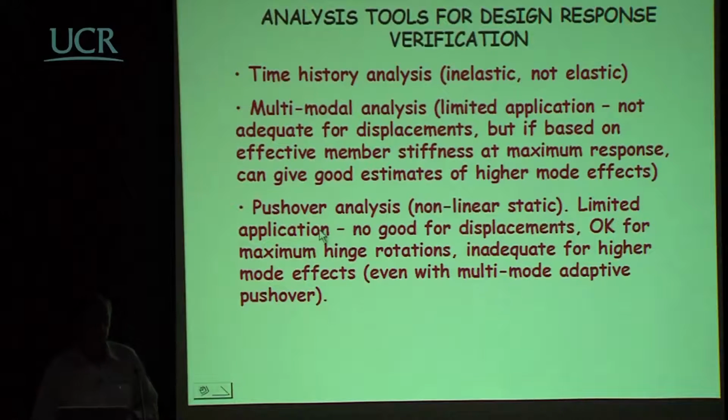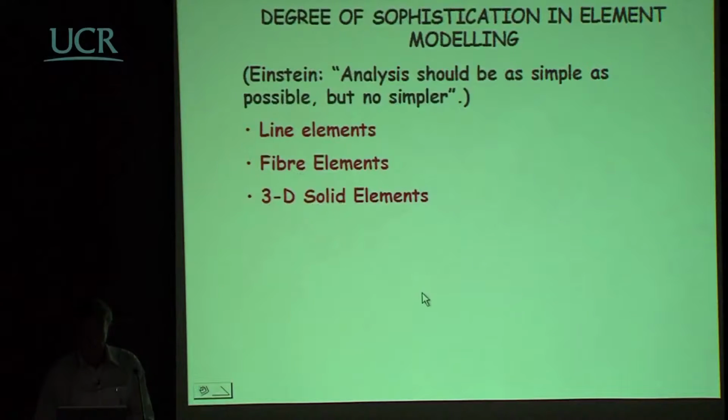It must be used in an adaptive pushover fashion, which means that you've got to modify the shape of the force vector or displacement vector that you apply as the structure deforms. It's very difficult to incorporate higher mode effects. There are techniques being developed, but they're even more complex than doing a time history analysis, so there's no real reason why we would want to use it.